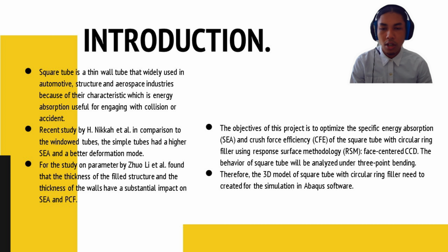For the study on parameter by Zoli et al., found that the thickness of the filler structure and the thickness of the wall have a substantial impact on the SEA and PCF. The objective of this project is to optimize the specific energy absorption SEA and crush force efficiency CFE of the square tube with circular ring filler using response surface methodology, face-centered CCD.